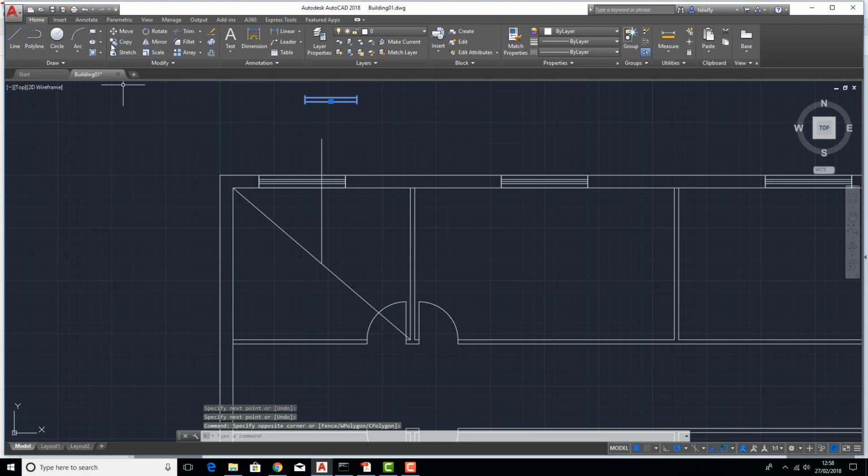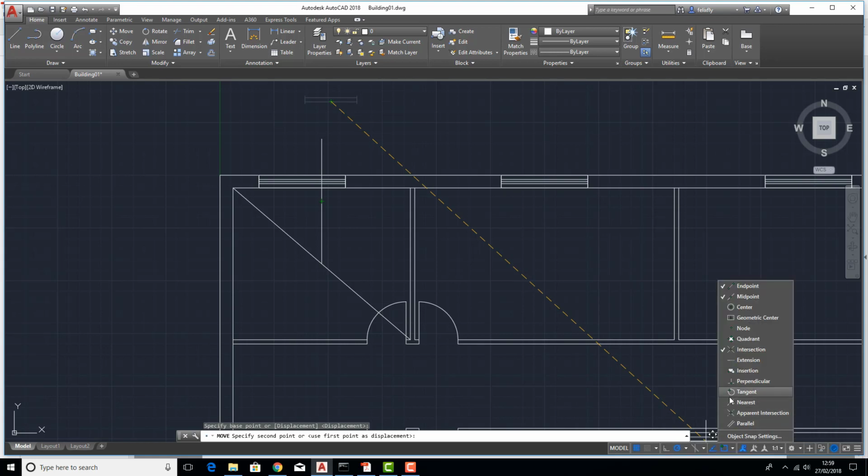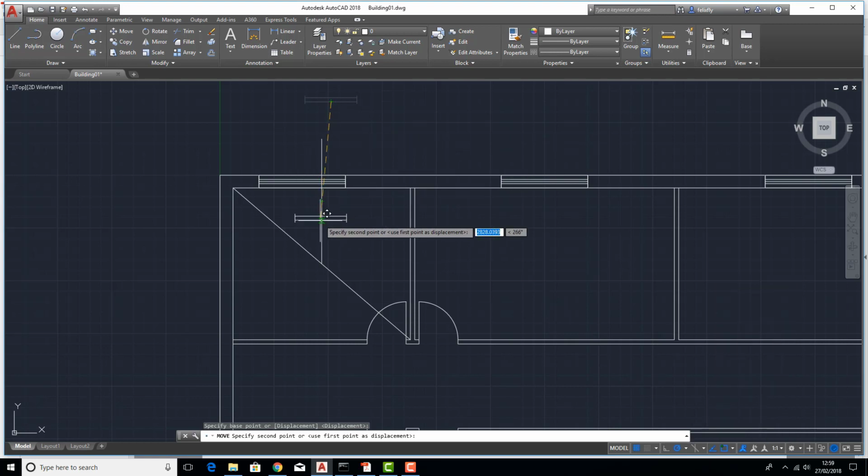And we will move this by grabbing the midpoint, and now this is snapping to the midpoint because we just drew this line in anyway really. The midpoint is there. I want this about here. What we can do, we have another one of these snaps called nearest, and that will just go to a line at the point nearest to your cursor.